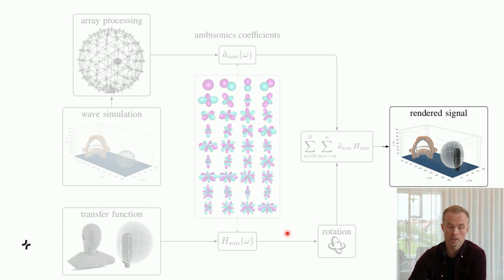And the nice thing about this is that in geometrical acoustic simulations, it would have been hard to include the device from the beginning. But this way you can actually include it in both geometrical and wave-based simulations, and you don't need to rerun a simulation to switch out the device or rotate it or whatever you want.